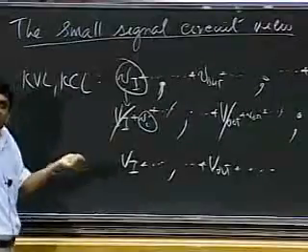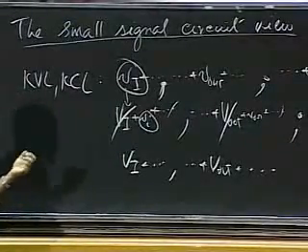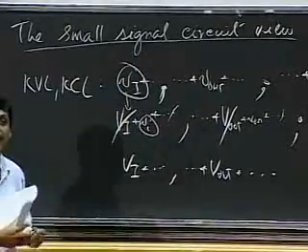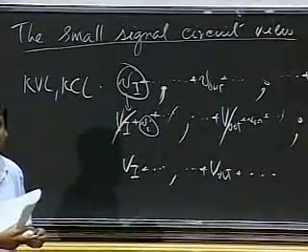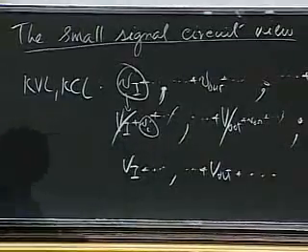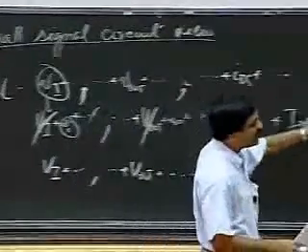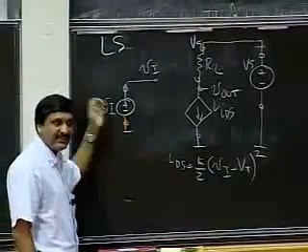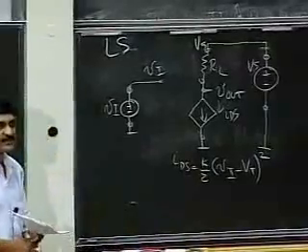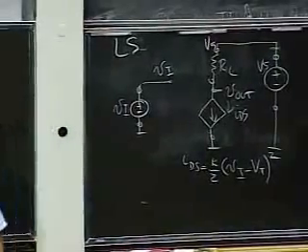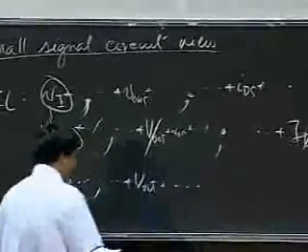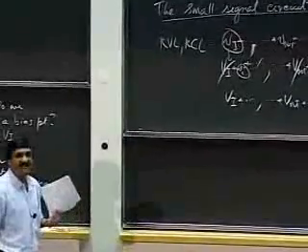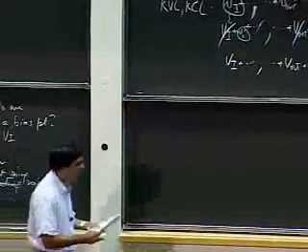Since these arise from the small signal elements, I can replace the big elements with the small elements, and KVL and KCL will hold for the resulting circuit. This is a very quick breeze through an informal proof to show that I can replace the big elements with the corresponding little element models, and then simply apply linear techniques. Refer to section 8.2.1 for more discussion about the foundations for why we can do this.